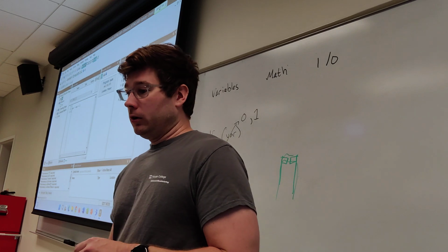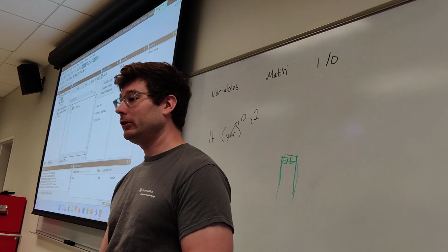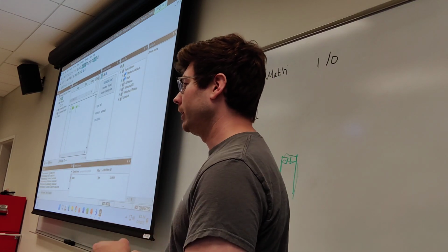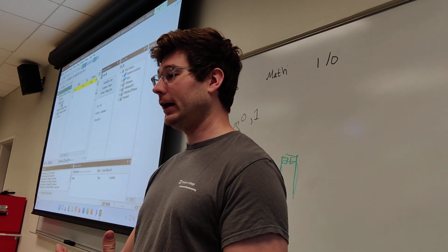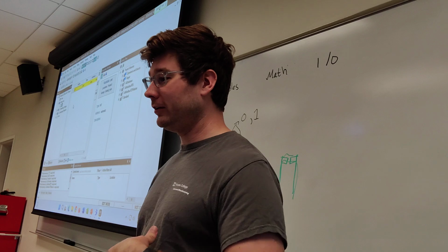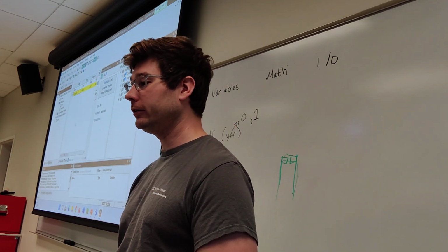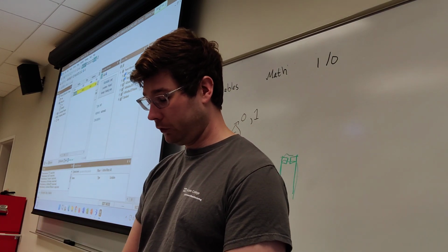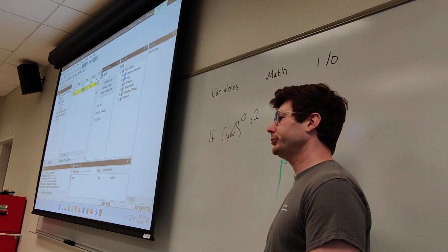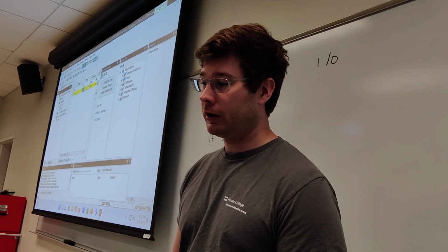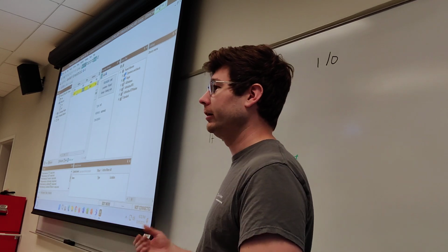Let's talk about more things. That CNT variable, where we are storing the number that we're counting up over and over again, is stored in our global variables right here. I double-clicked on this flag, and now we have essentially a mini Excel sheet that we can stick variables into. I can right-click here, click Insert, and create whatever helpful name I want. They can be helper variables storing useful bits of information, like a conversion unit. If you're converting Celsius to Fahrenheit, you might have a weird number stuck in there for doing math with.